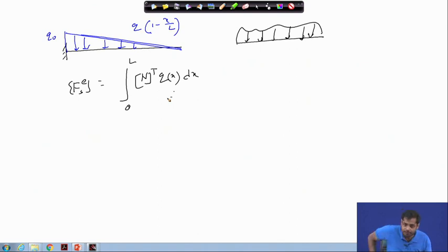obtained the stiffness matrix at the element level and also the load vector at the element level, next we have to assemble these stiffness matrices. Not only the stiffness matrices, we have to assemble the nodal load vector as well, exactly the same way we assemble the stiffness matrix. Okay. But now it is just in a vector form. So, once we assemble them, we get a global stiffness matrix and the global load vector. Then we have to do partitioning, and with the information of boundary conditions, we reduce the stiffness matrix and calculate the unknown displacements, right.